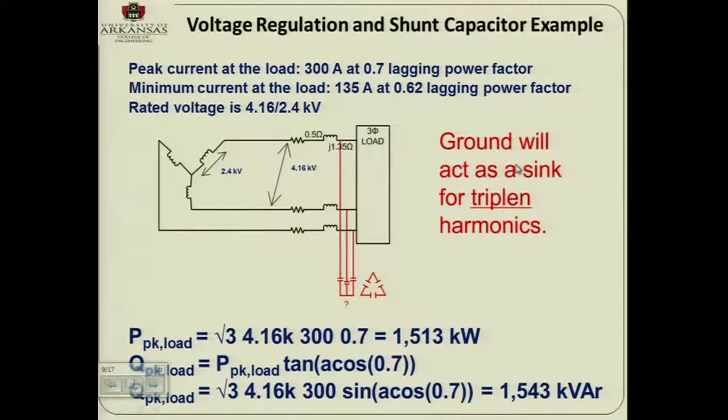And what happens with heat inside a capacitor? A capacitor has an electrolyte between the two plates. And what happens with heat? It will basically evaporate the electrolyte until you get a disaster, right? That's the reason why I have the delta next to that. Because if you have a delta connection, the capacitors won't be subject to triple harmonics.